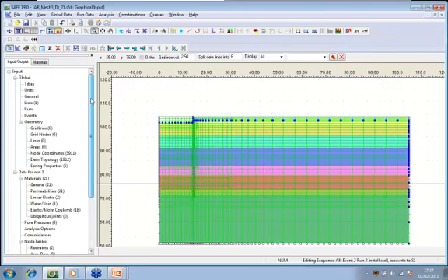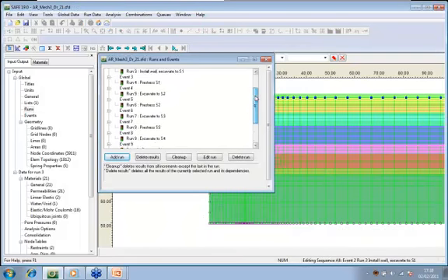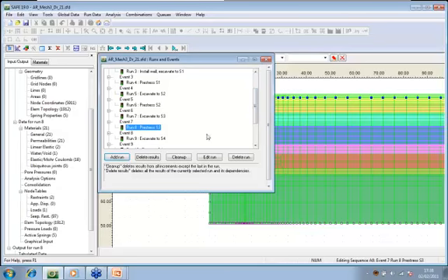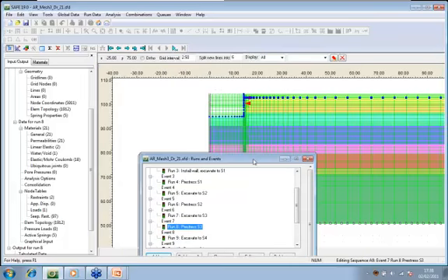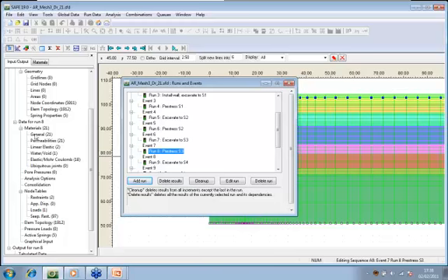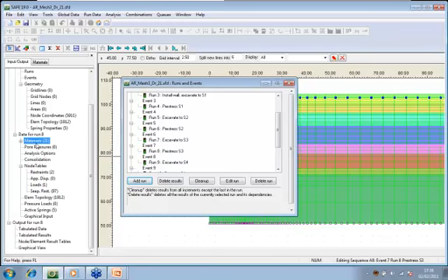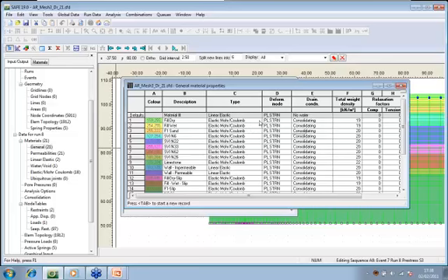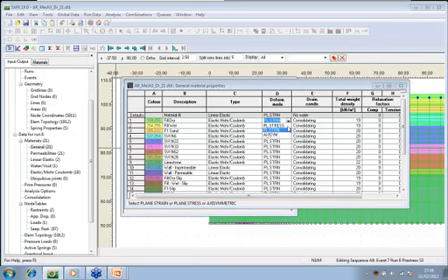If you look at the SAFE here, this is probably interesting for a lot of you in that this is the gateway inputs, and you can have a look at your runs. And I could choose a specific run. Say, for example, I wanted to see the full excavation, so I could choose that run, and that would change what's going on in my mesh here. You can see the prop and everything here. You could also specify materials, so I touched upon this, but say, for example, this is a plane strain problem, but I can make it a plane stress or an axisymmetric problem. I can look at different conditions, the drained, the undrained, the consolidating.